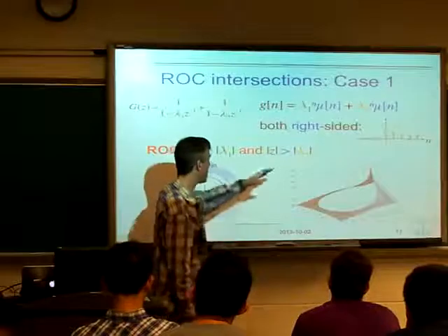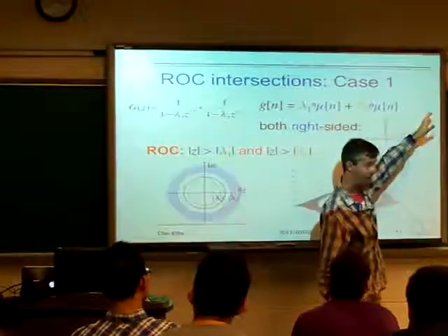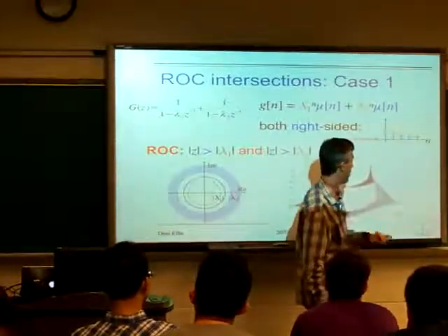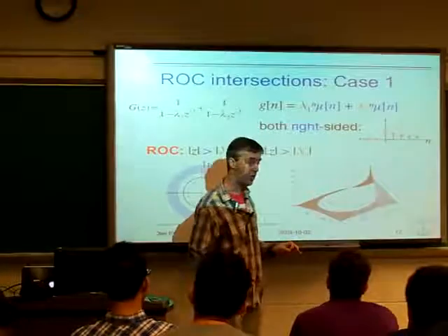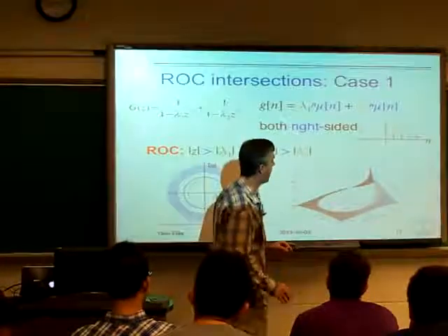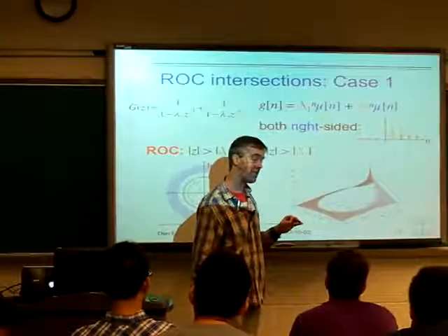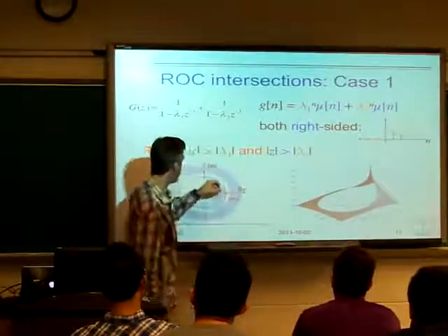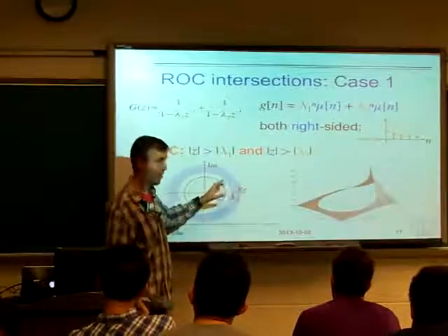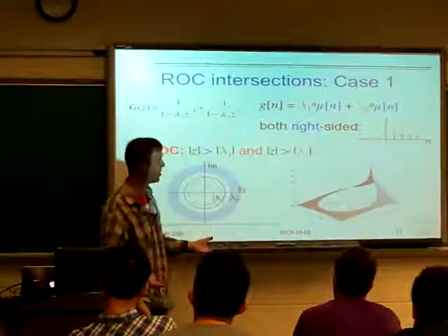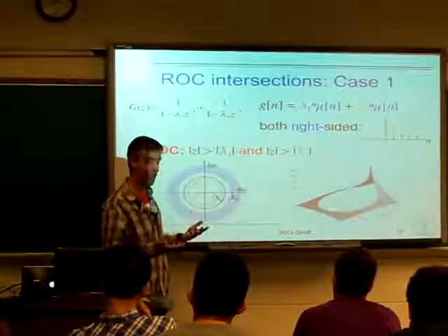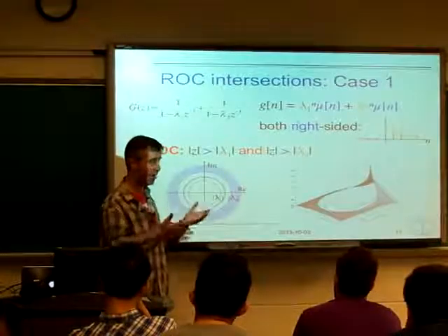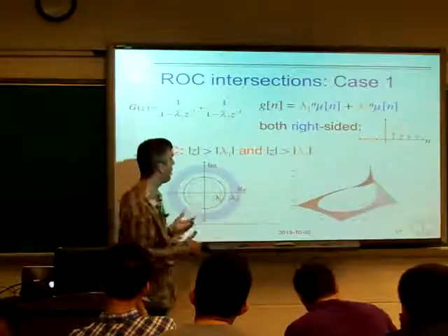So that's fine. We've got a sequence here. The sequence is not bounded, right? The values get larger as you go on, which means we'd have a lot of trouble taking its Fourier transform. We said the Fourier transform was evaluating G(z) on the unit circle. This solid line here is not within the region of convergence. That is, G(e^jω) is going to be one of these nasty divergent infinite values.